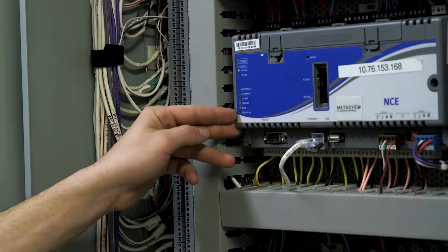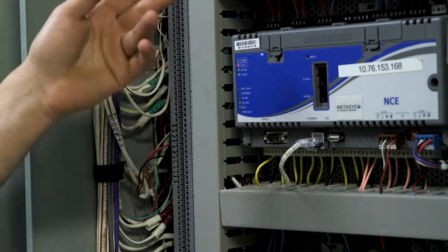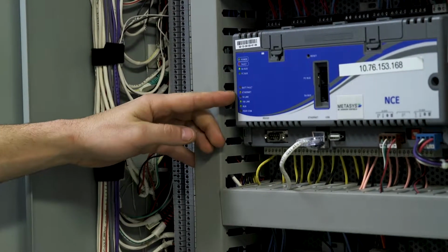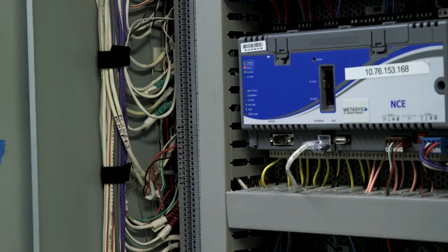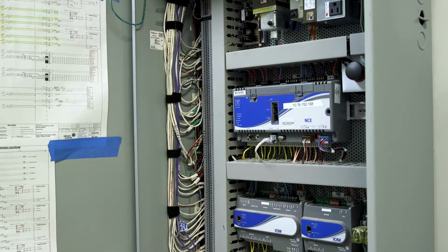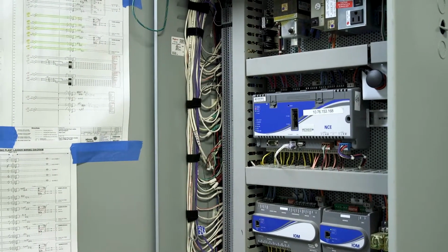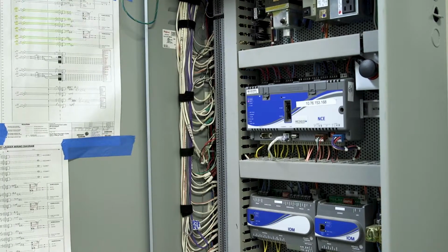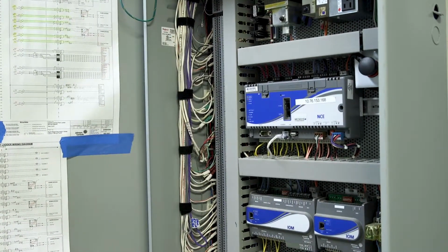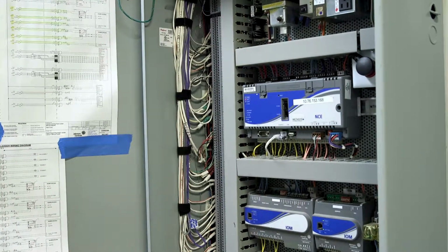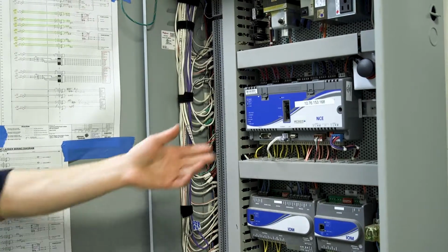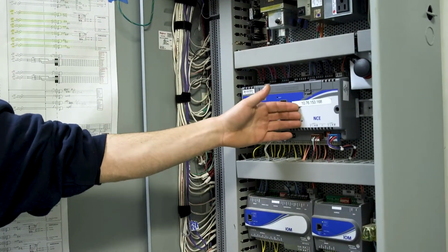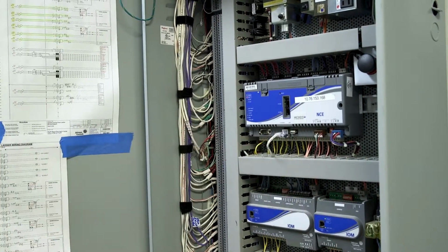And then this is just your connectivity lights, what speed you're running at, making sure you got your Ethernet blinking, which means you got connectivity. Burned-in memory, so things like certain programs, what address am I and everything, are burned in the EEPROM. That battery keeps the EEPROM, so when you lose power, it helps keep that memory. Like right now, if you pulled the battery out, it wouldn't do anything only because you're on live power. That's why, if you had to reset, say this went into a fault and you tried to do a reset and you shut the power, it's gonna stay on. You're gonna have to pull the battery and put the battery back in.